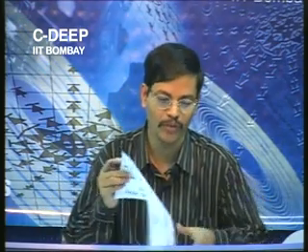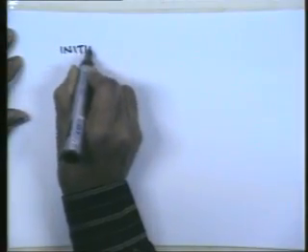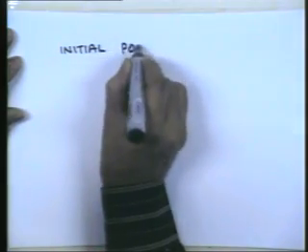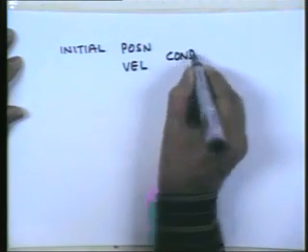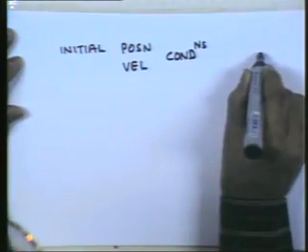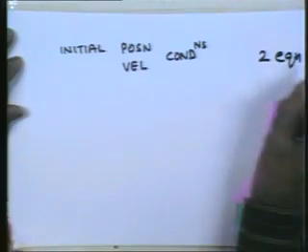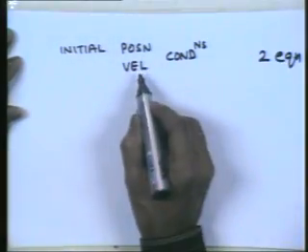Four into n plus 1 equations are required. Now, how do you get these 4 into n plus 1 equations? It's essentially the same as what we discussed with the example of 3 general points, expanded to any number n of intermediate or via points. So, at the initial position and velocity conditions, you will have 2 equations, right, initial position and initial velocity.